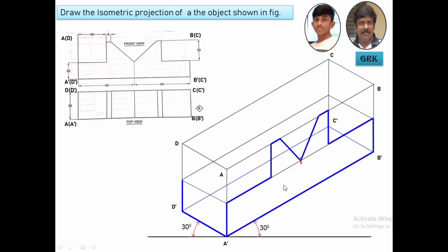Now you can draw all these lines where the parallel lines are the isometric lines. What do you observe here? All these lines are parallel. See, I told you I am standing at this corner, therefore this top line could be marked. So measure that length, it's 30 mm, and it is 30 already, it has been plotted. So you can join this line in the same plane, in this plane. So one by one you join it. It goes and touches the lines that have already been created.